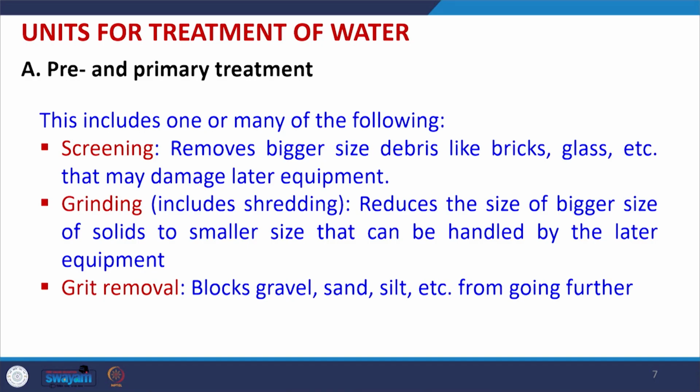So, the first step is screening. This screening removes the bigger size debris like bricks, grass etc., that may damage the later equipment. In the second step, grinding including shredding reduces the size of bigger size solids to smaller size that can be handled by the later equipment. Similarly, grit removal blocks the gravel, sand, silt etc., from going further.